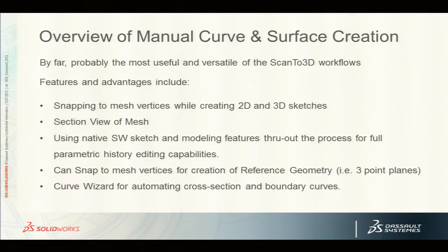And we also have some other tools in there, like Curve Wizard. If I have a mesh, I can use the Curve Wizard tool to make an automatic multi-curve section of that mesh. And then I can use those curves to model a boundary surface over that mesh.